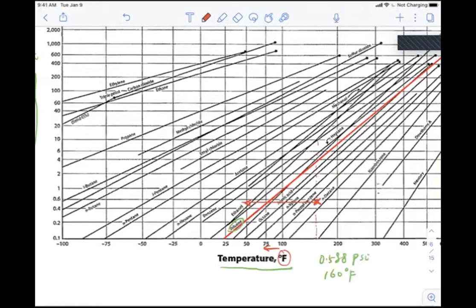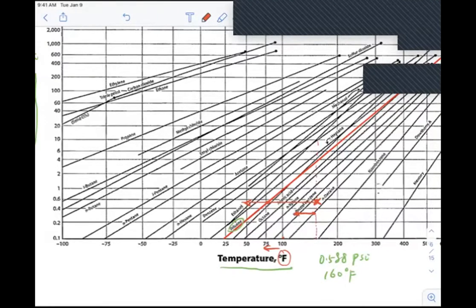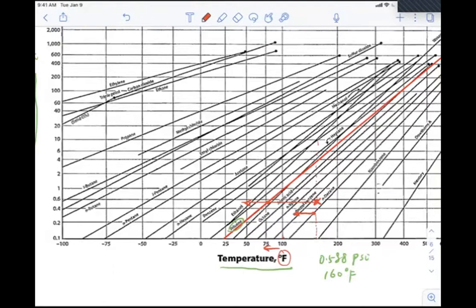Let's say at the beginning of the cooling process, the toluene is not going to condense at all. Let's say it cools down until around 100 Fahrenheit. The toluene is not going to condense because its partial pressure is still lower than its vapor pressure. So the toluene is still going to keep its vapor form and flow happily in the gas stream until it hits this point, where it reaches the vapor pressure. So what's going to happen next if we further cool down the temperature?